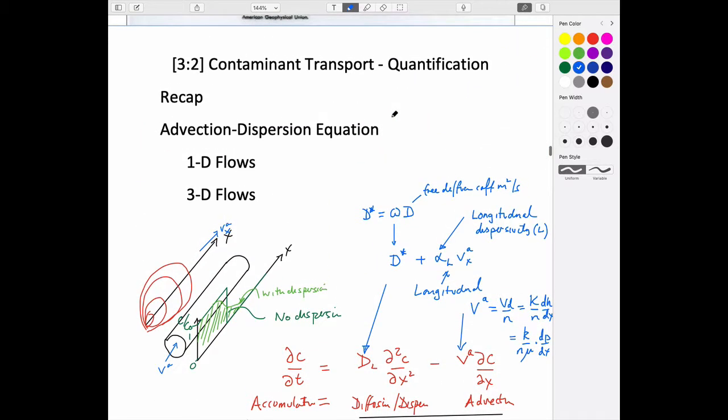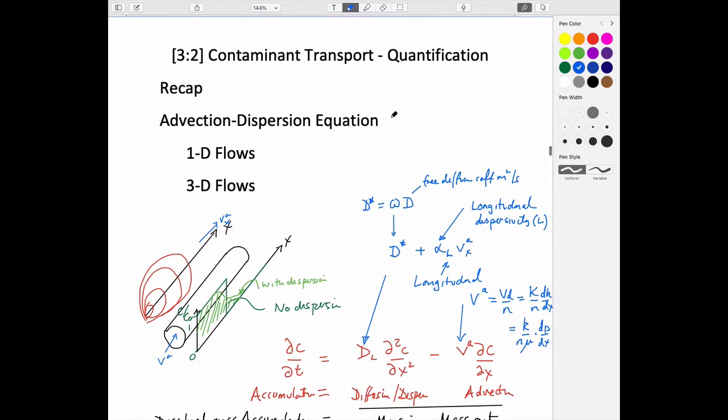And we made the case last time, even though I'm kind of running out of space here, that if you looked on a spectrum of different materials, maybe from sands and gravels to clays and shales, as rocks that have the permeability of shales, then the velocity at this end is small, and the value of this longitudinal dispersion, which we're interested in here, would be approximately equal to D star, because if velocity is small, this term drops out.